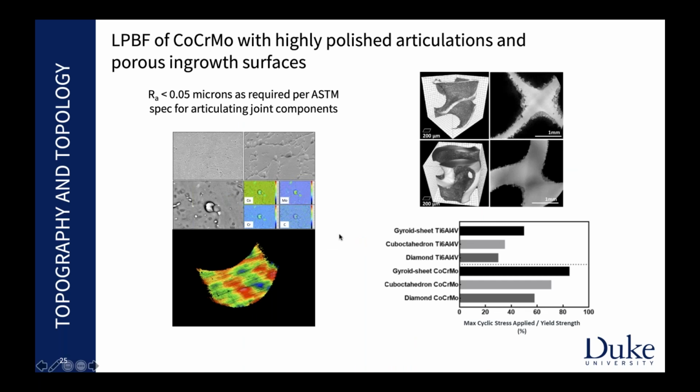I forgot to mention those were all titanium alloys that we were looking at in the first one. But what we found with cobalt chrome is it's used in the body mainly because of articulating surfaces. So you can actually polish them, highly polished, to articulate with other joints or in hemi-arthroplasty or articulate with other metals in full arthroplasty. And the cobalt chrome actually, and we don't understand why, prints really, really well. So it prints much better than the titanium.